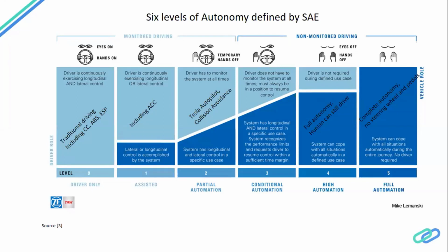And then you have the first level vehicle, where only one particular dynamic of the vehicle is controlled. It can be the lateral direction, which is your y direction, or the longitudinal control, which is your x direction. What I mean by lateral or longitudinal control is, for example, automatic cruise control. Automatic cruise control basically maintains the distance and speed with respect to the vehicle in front of you, so you do not get close to it when you are driving.